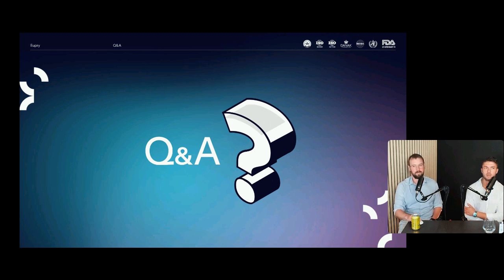Yeah. I think also a very easy one to get around in terms of what you need to be aware of is obviously the equipment you use for performing a mapping. Check that the equipment you're actually using for performing the mapping has been calibrated and is within accuracy, so that you can actually trust the data that you're seeing.